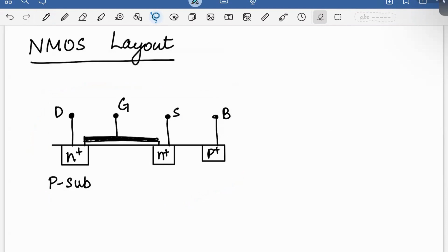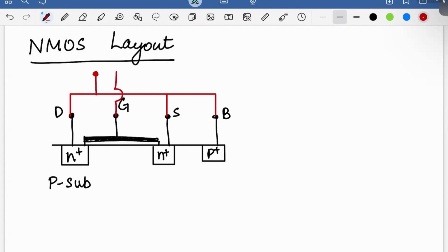Okay. So typically in a MOS varactor, this is just a general MOS varactor. The way it's made is that you connect the source, drain, and body together, and that gives you one terminal of the capacitor, and then the gate gives you the other terminal, right? Something like this. Okay, so that's your two-terminal capacitor.